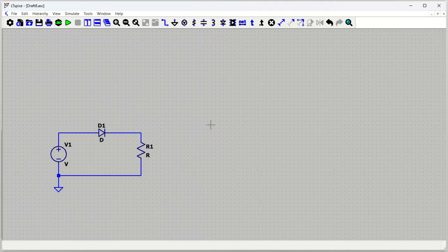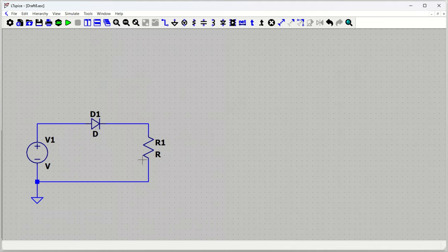Now the other thing that comes up is, let us say I want to move this particular resistor a little bit, to this side or that side. So there is a move function or something like that. This is the copy function, duplicate. Suppose I want to copy this resistor. So I'll just put this one. This has been copied, and one more copy. Again, if you want, one more copy. Like that, keep on copying one by one, and then press escape. So all the same values, if you wanted to copy, it has copied.